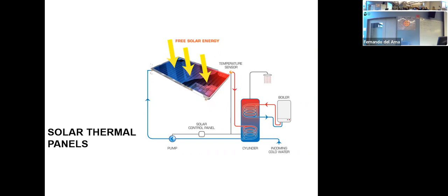And then we have to reduce that water by mixing it with the cold water. Okay? But we need to kill this bacteria here. So the temperature that goes out from this tank has to be at 140. But if we have another circuit with radiator or radiant floor or whatever, the temperature here probably can be 100, 120 Fahrenheit. The temperature through radiators or radiant floors.